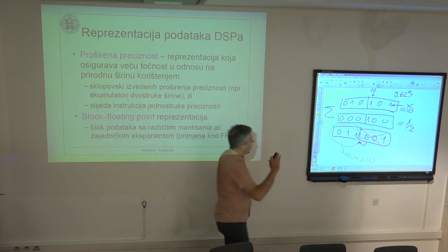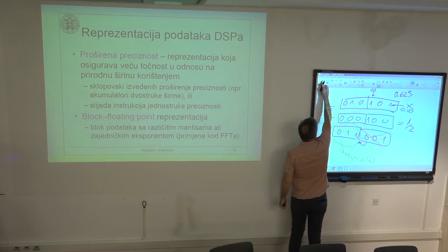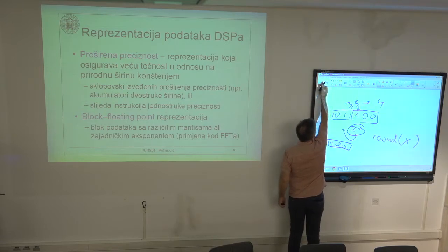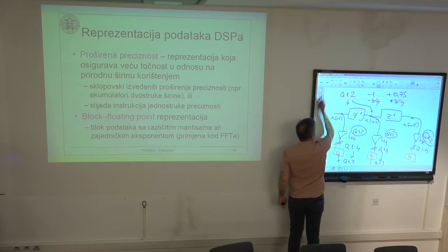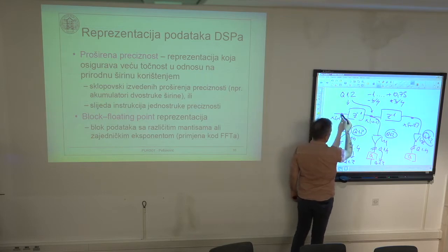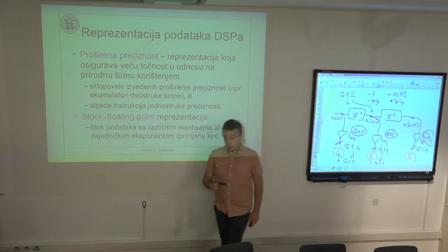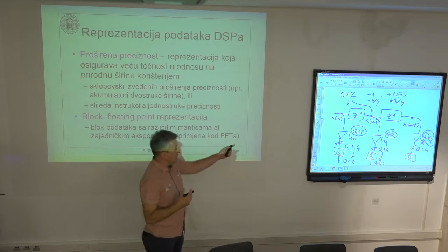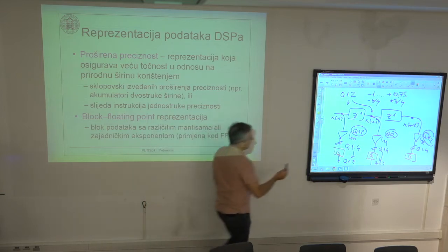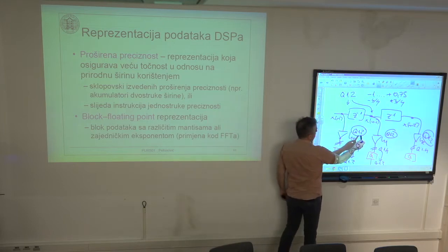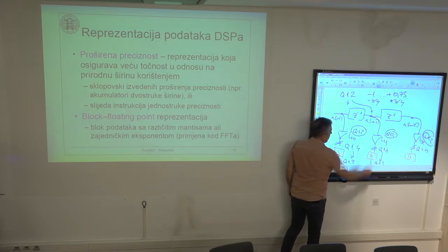Okay, but going back to the original idea. We started from this architecture of a digital filter. We have the filter states, which are actually input samples that are delayed by 1 step, by 2 steps, and so on. These filter states are multiplied with coefficients H0, H1, H2.